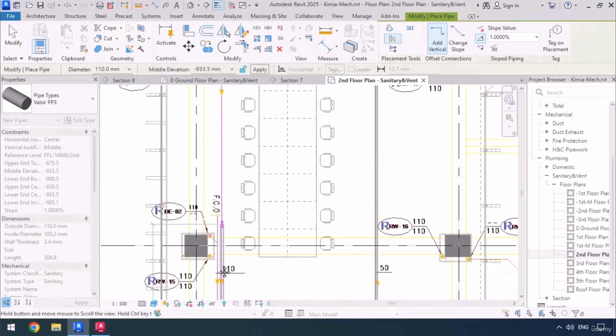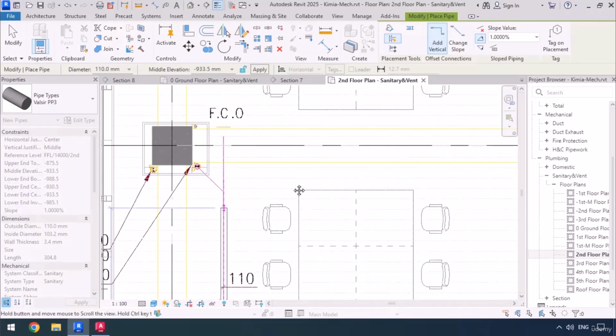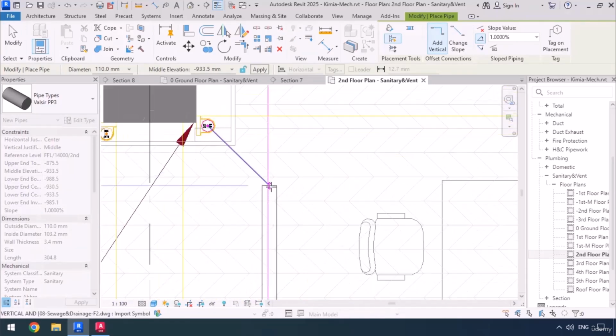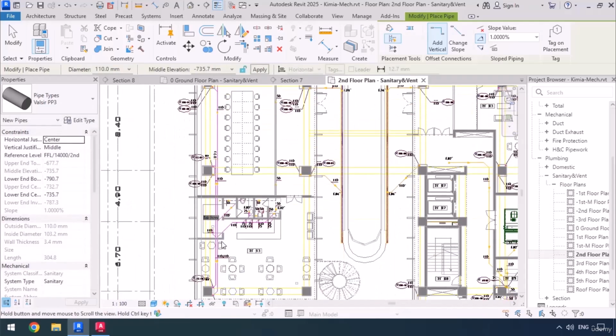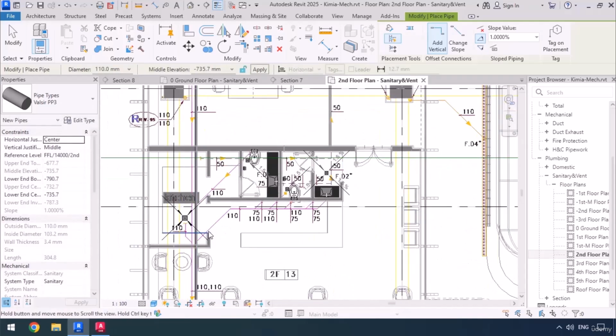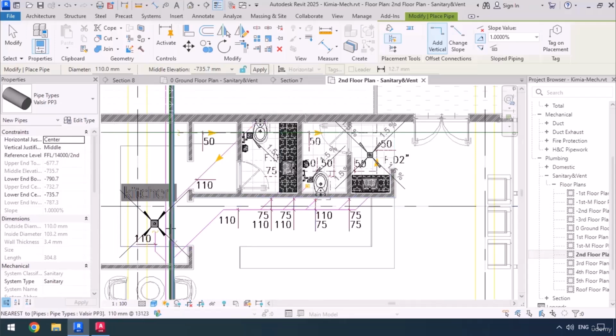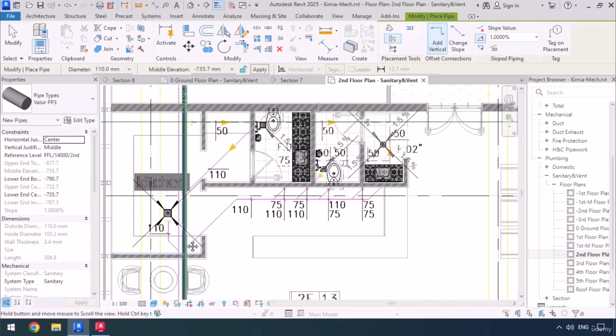We're going to go all the way up to riser number 8, where once again it changes directions, click and click. Now, along this pipe's way, we've also got some sanitary pipes, which are related to this restroom area, all of which will be connected to this riser.